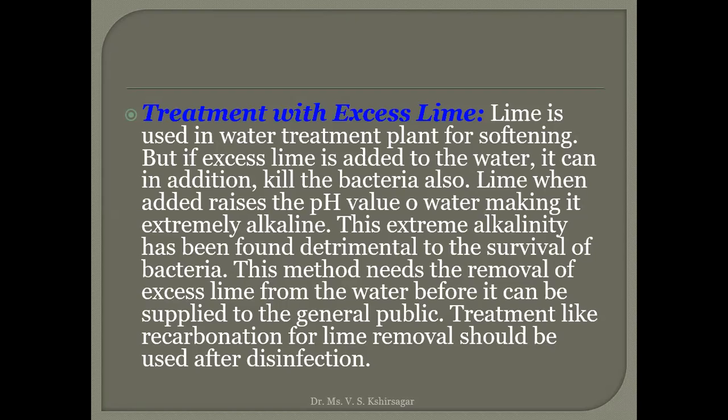I don't know how much you understood through these lines. I will explain. Okay, use of lime is for what purpose? For water softening purpose. Okay, so carbonates and bicarbonates of calcium and magnesium react with lime and they convert into PPT, that is precipitate, and start settling down.